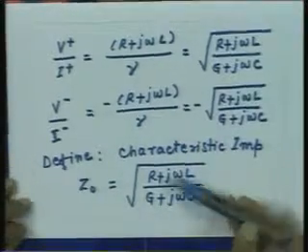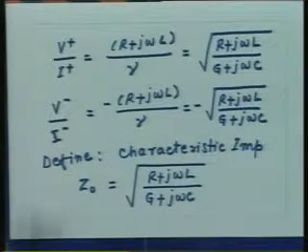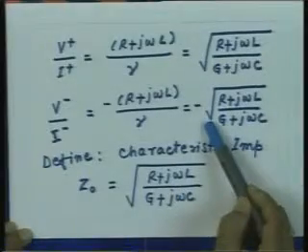So, again concluding that irrespective of the boundary conditions on the transmission line, we established that the forward travelling wave always sees ahead of it the impedance which is equal to the characteristic impedance, and a backward travelling wave sees the characteristic impedance if I look backwards, but if I look forward, then the backward travelling wave will see an impedance which will be the negative of the characteristic impedance. So, as I mentioned, these two quantities, gamma and Z naught, are adequate to solve the transmission line problems.